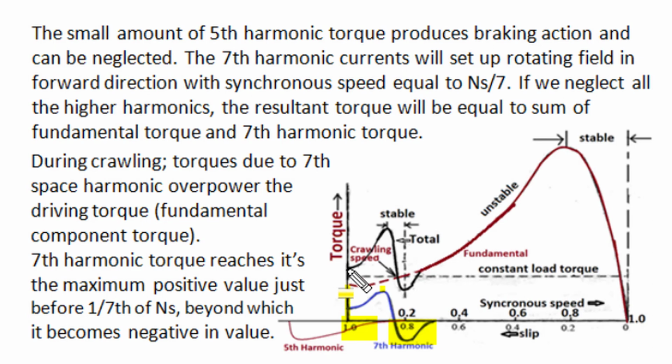then the resultant torque behavior will have a saddle characteristic, and this resultant torque attains a peak magnitude and then gets a negative torque speed characteristic for a certain region. In this negative torque speed relationship there exists a stable operating point, and if load torque matches these motoring torque conditions, then a motor can rotate at 1/7 of synchronous speed, and that slow speed rotation is called crawling.